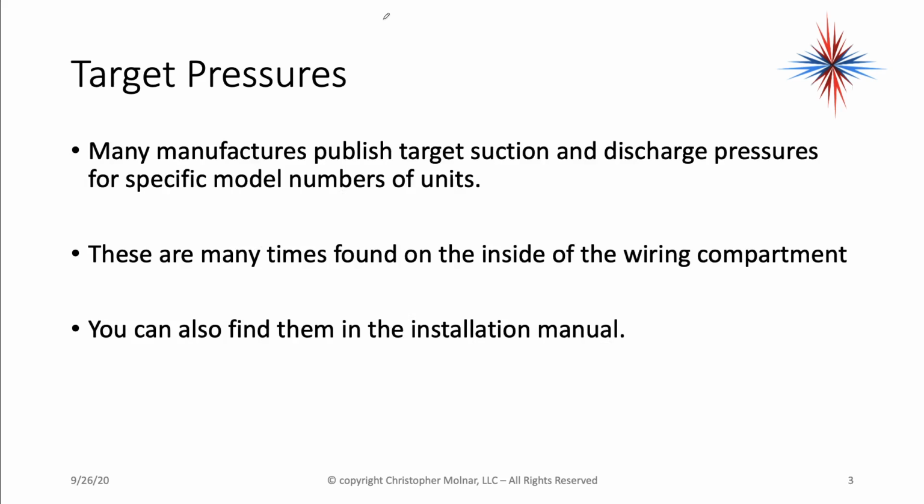Now, let's start off with target pressures. Most manufacturers publish target suction and discharge pressures for a specific model number of units, okay? They're many times found inside the wiring compartment, or you'll also find them in the installation manual.